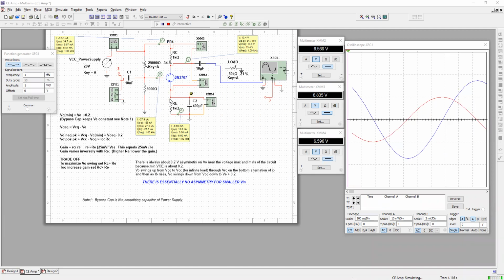We also understood that the emitter resistor provides negative feedback so that if there's any drift in the beta or the HFE factor, it would be compensated for. The voltage in the emitter would rise or fall and contract or expand the voltage at the base to emitter junction. Now we're going to look at the input stage. And when we do that, we're going to enter the world of AC operation.